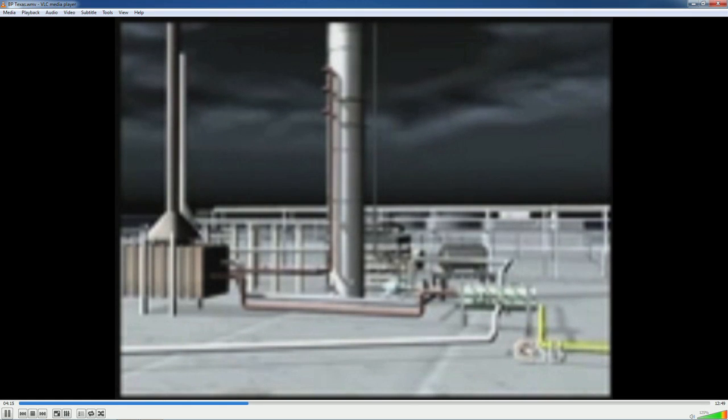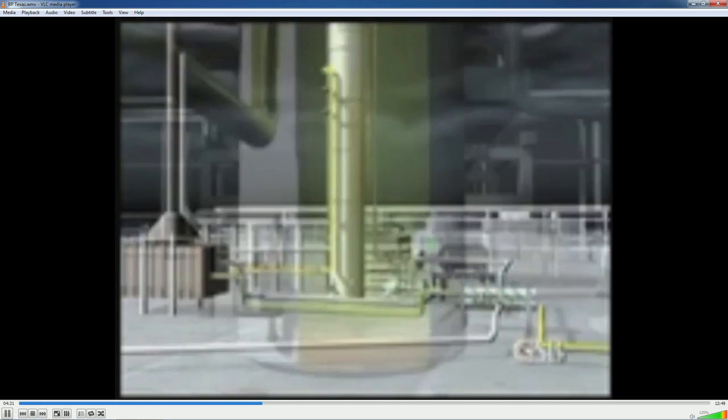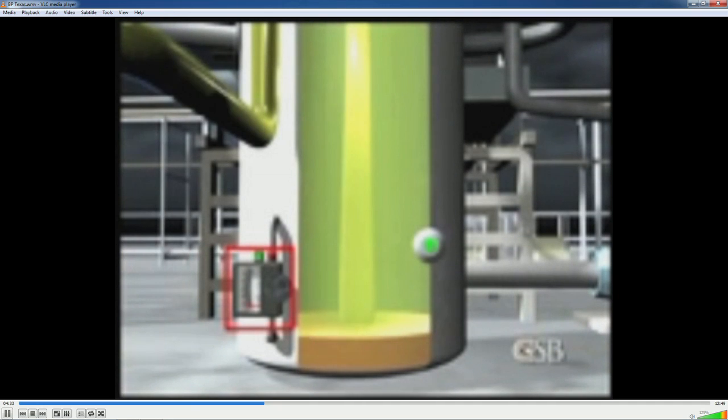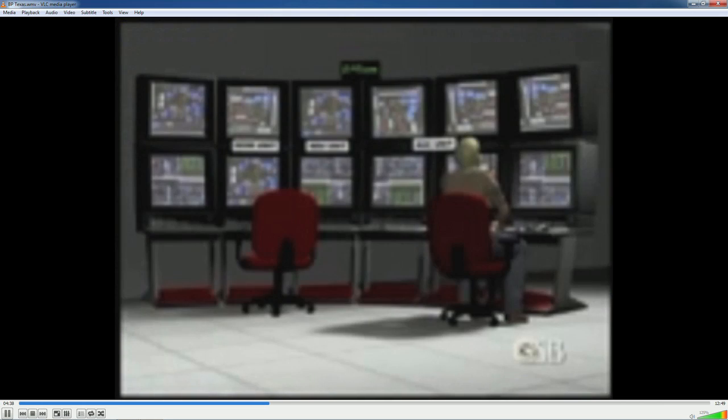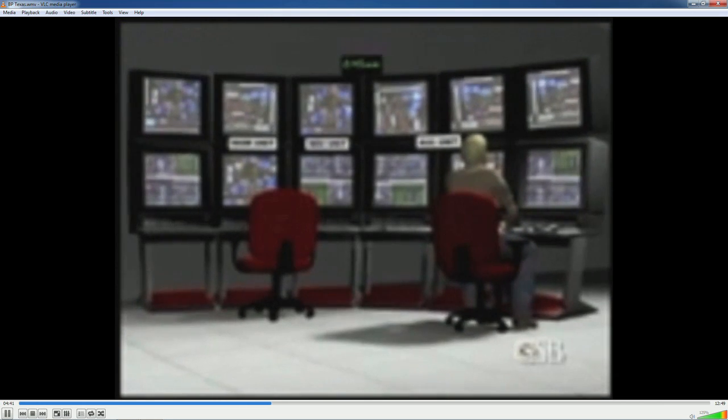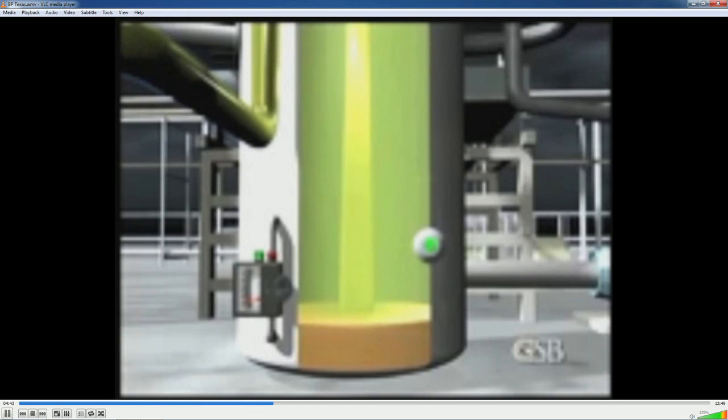At 2:15 a.m. on March 23rd, overnight operators began introducing flammable liquid hydrocarbons known as raffinate into a 170-foot tall raffinate splitter tower used to distill and separate gasoline components. Near the base of the tower, there was a single instrument that measured how much liquid was inside. It transmitted this information to a central control room located away from the ISOM unit. But this level indicator was not designed to measure liquid above the 9-foot mark. During normal operation, the tower was only supposed to contain about 6.5 feet of liquid.